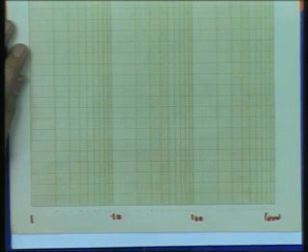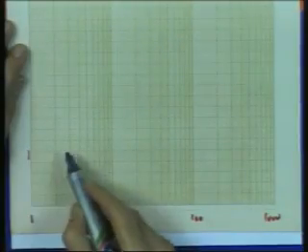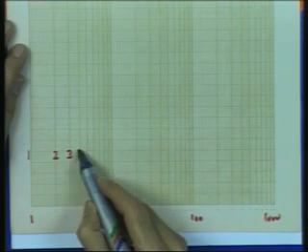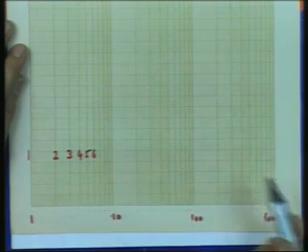except when I talk about corner frequency I have to be careful about the choice between omega and f. It is omega which is equal to the absolute value of the real zero or the real pole, not f. So, if I keep that in mind, there is no problem. And now we can see that the spacing is going on decreasing. Here is 1, here is 2, here is 3, 4, 5, 6 and so on. So, in fact, they are getting very close.